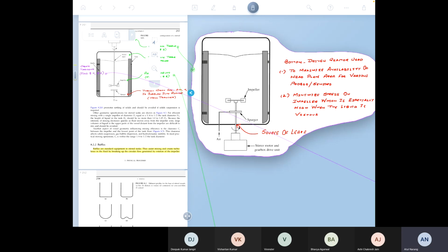And these systems actually are much more stable in the sense that the stirrer shaft is much less likely to break if you have a very viscous culture. But otherwise, the default one, I mean, the research lab has practically only top driven fermenters.